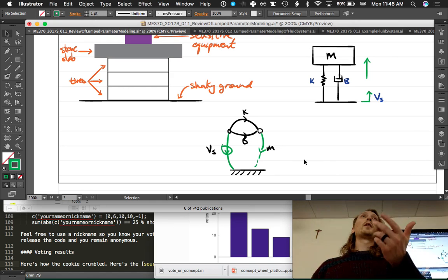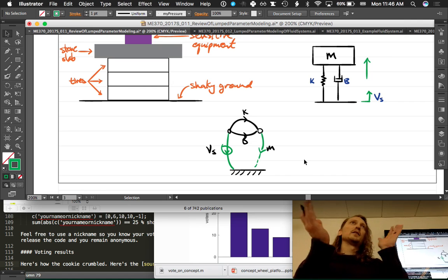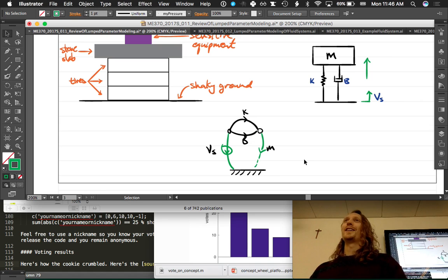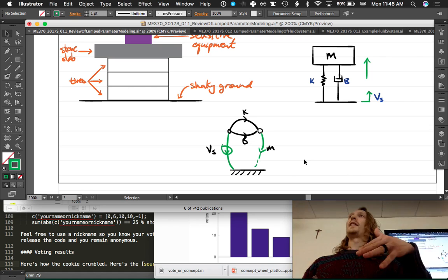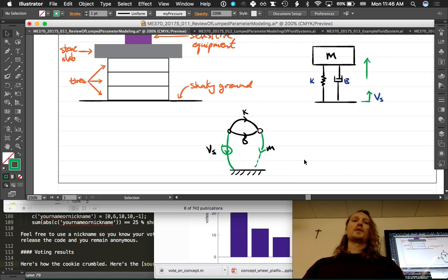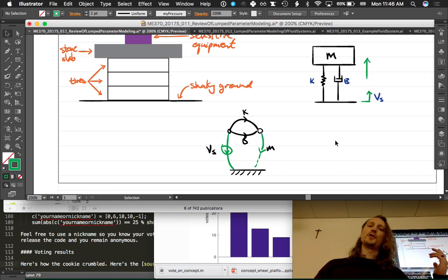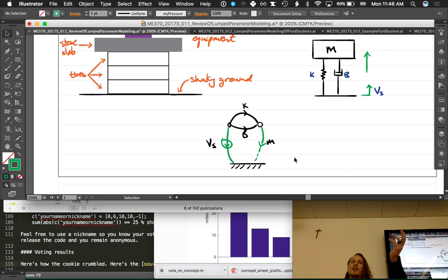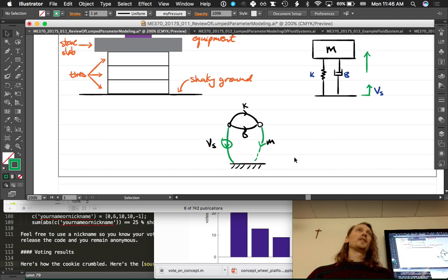The next priority would actually be transformers or gyrators, right? We don't have any of them in here. And then after that, it's D-type energy storage elements. But notice that we don't have any room for anything. If we select either of those two, we have created a loop, and it's not a normal tree anymore. So now we would be able to launch into the automatic procedure that we know and love, right? Yes.